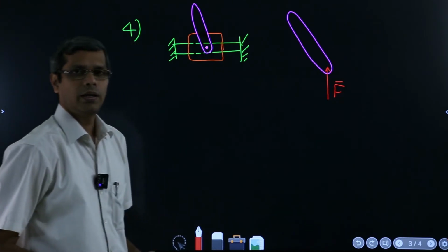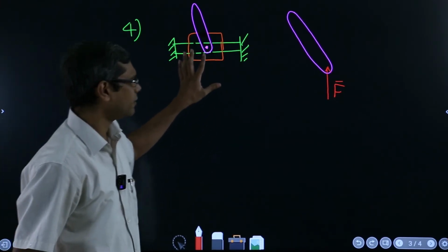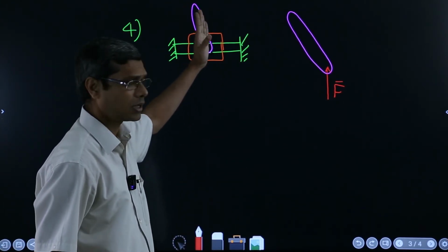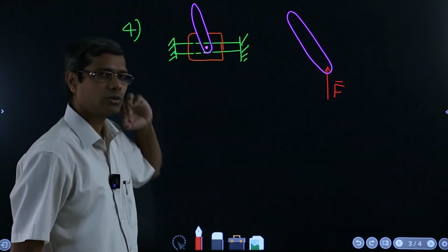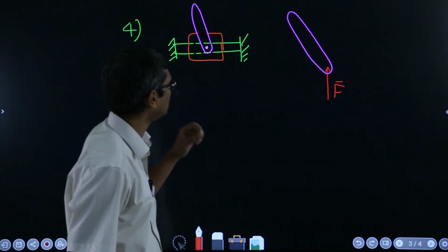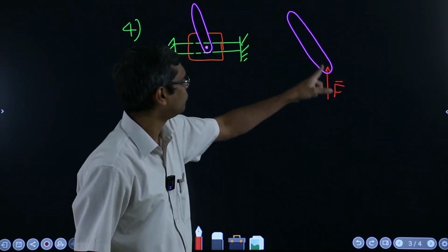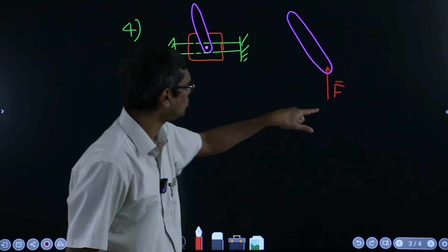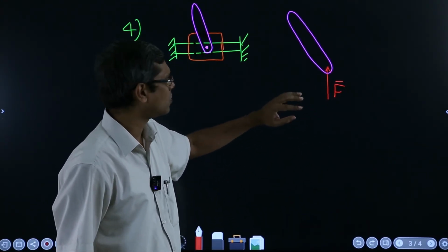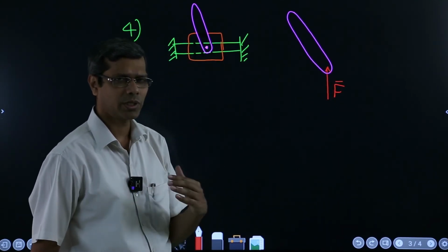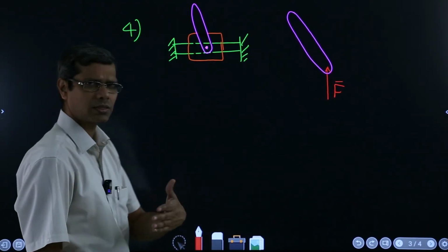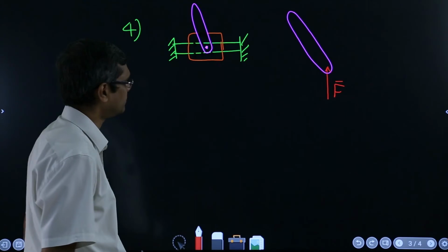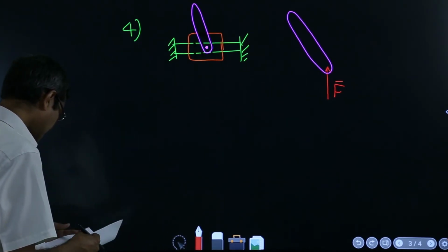That is a very important connector, the freely sliding connector, and it doesn't depend on the angle. Students make this mistake a lot of times, that they feel the force will come in this direction. No, it doesn't. In the free body diagram you have to show the picture like this. Maybe the component in this direction will do something special, which we will come to in the next segment, but when you show the free body diagram it will have to be like this.